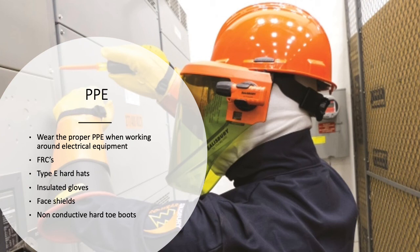Type E hard hats, which most of us have in the oil field. The MSA V-Guard that we wear are typically Type E, which protects against 20,000 volts or your typical overhead power line voltage. Insulated gloves are also important, insulated boots, face shields, and non-conductive hard toe boots.